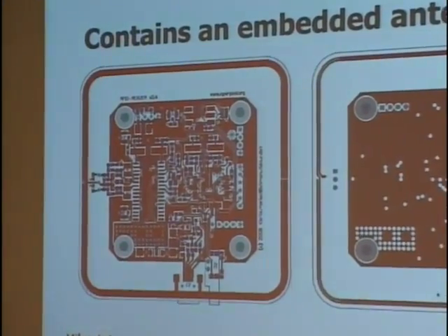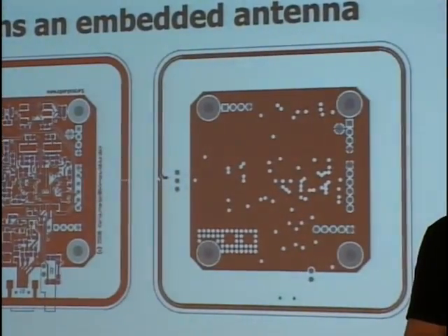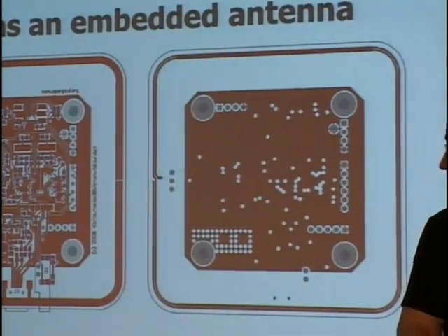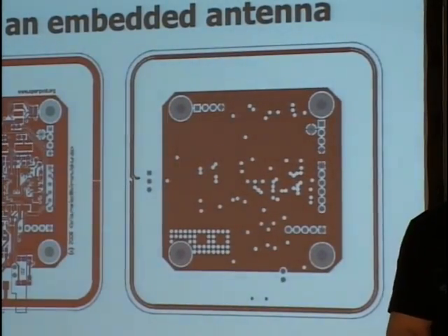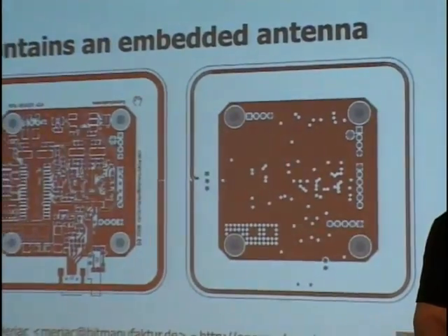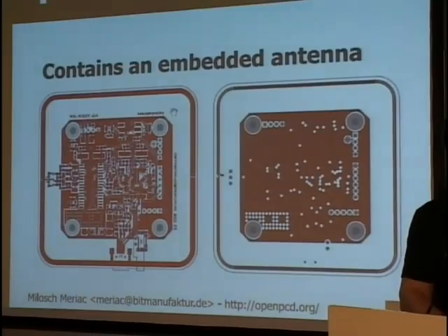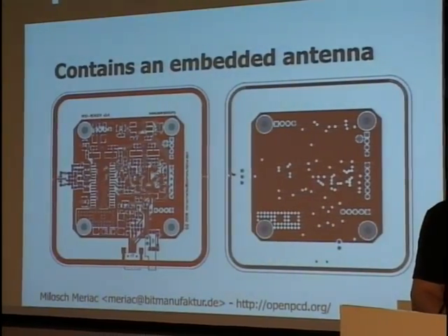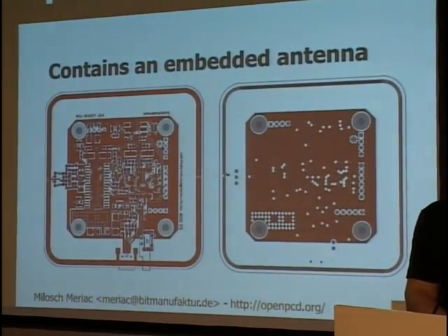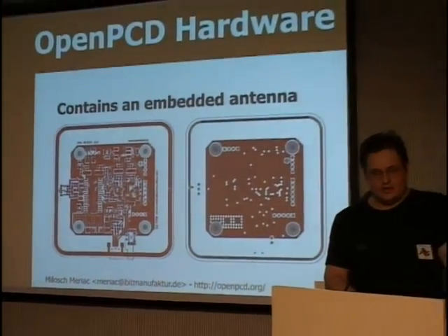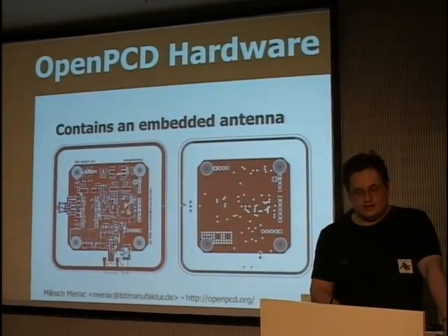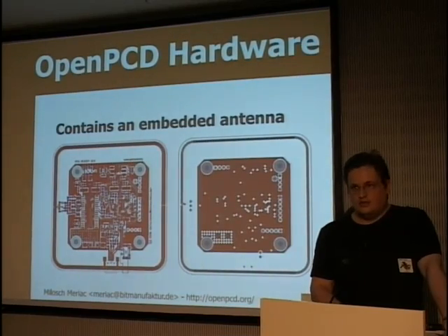The second one is the intermediate layer, where you have 2 turns of the 4 turns. You can see them on the dark red part. You also have the possibility to adapt it to external antennas. We used 0-ohm resistors to connect this antenna. You just remove them, and you have a 3-pin 2.54 millimeter spaced header to connect another antenna and do whatever you want. So basically, you have to do your own antenna adaptation in this case.